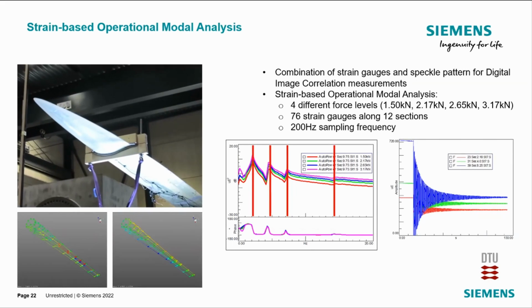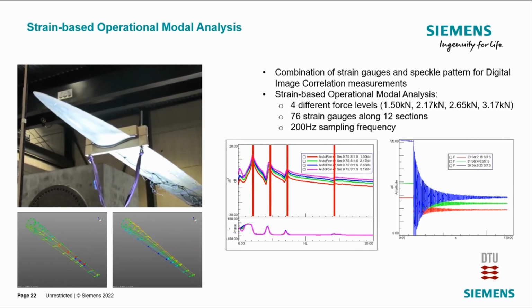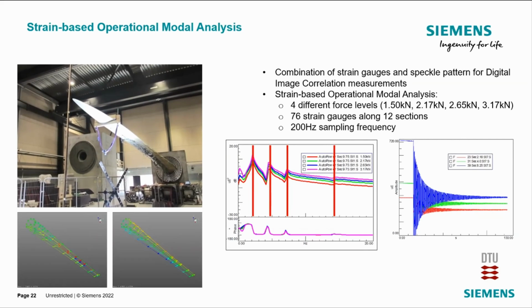So our company is quite well known for this, the modal analysis capabilities. So we do have this PolyMAX to identify the modes. In this case, we go operational, so we don't know the input. The structure is running continuously, and then we use the operational modal analysis. And moreover, we don't look at classical accelerometer-based measurements, but we look at strain gauges. And then we were able, indeed, in this case, to identify most of the modes we were interested in, because the frequency range is pretty low, and strain gauges were enough to cover such a frequency range. And then we are able also to plot, that's what you see here on the bottom left, the strain mode shapes, which identify where the higher strains are in the structure.